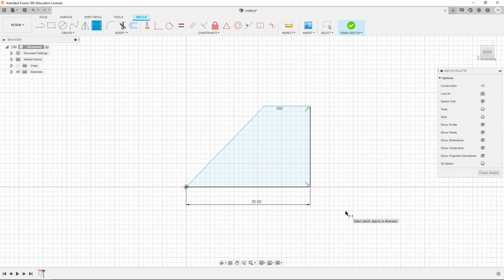We'll also notice as we force dimensions, lines will change from blue to black, and this means that they're constrained enough that they cannot move. So I cannot grab this vertex and drag it, because if I try to pull it this way, that would imply that this is not the correct measurement. But I've told it must be 26. I can't bring it in because that would make it smaller, and it can't be done. So the constraint dimensions are a form of constraint, limitation, saying you must be 26 millimeters.